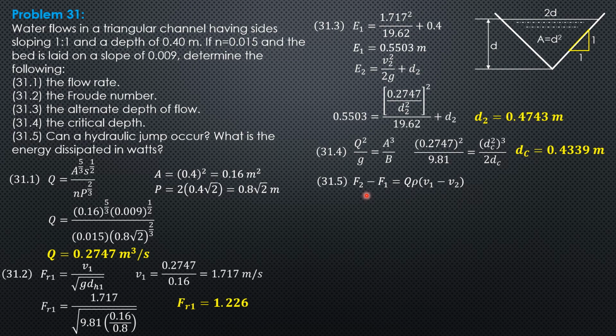So this is specific weight of water, times h bar, times area, where h bar is depth over 3 because this is a triangular section. So the distance from water surface to centroid is 1/3 of depth. Then the right side, cubic meter per second times density times meter per second is newtons. The left side, if you use 9.81 for specific weight of water, is kilonewtons. So we divide the right side by 1000 to match the units at the left side, kilonewtons.